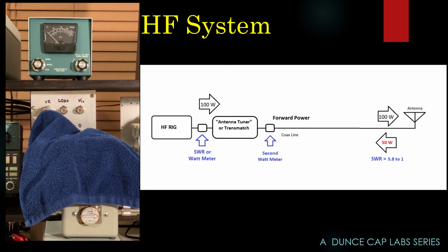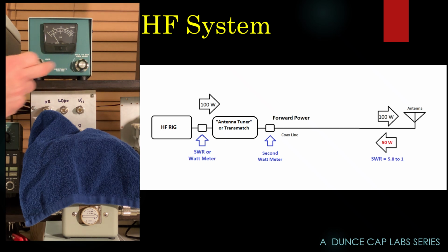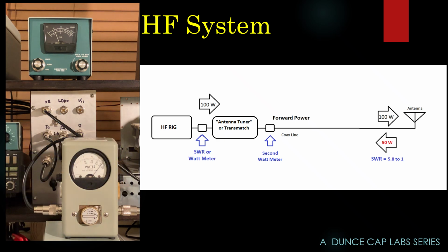All right. I'm going to calibrate my meter. My SWR is almost 1:1. And now it shows 100 watts. At the 100 watt level, this meter turns out to be rather accurate, even on the 2000 watt scale. 100 watts is actually just about right. What do we have at the output of the tuner? Okay, that looks like about, this is a 250 watt scale, about 225 watts.